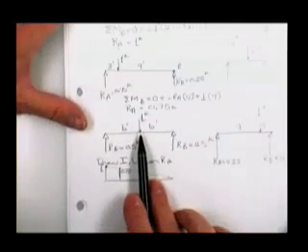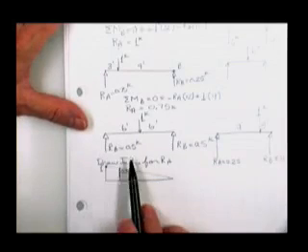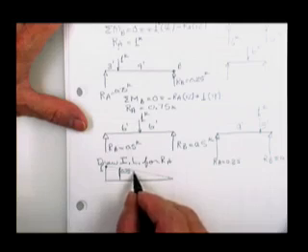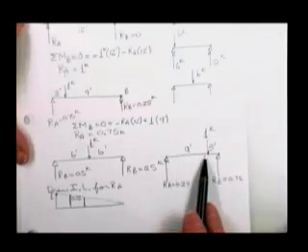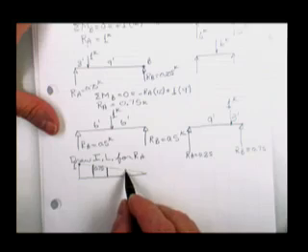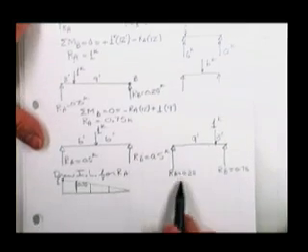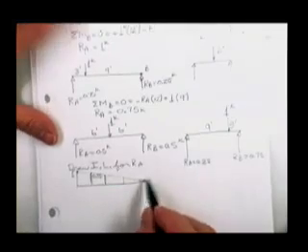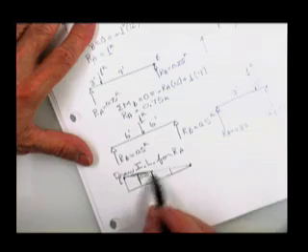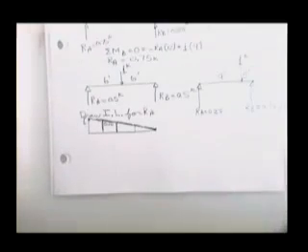And when you move the load to the middle of the beam, the reaction over on the left-hand end went to 0.5. And when you move the load to the 3/4 point, the reaction on the left-hand end went to 0.25. And when you move the load to the end of the beam, the reaction on the left-hand end went to 0. That is an influence line. It's not a shear diagram.